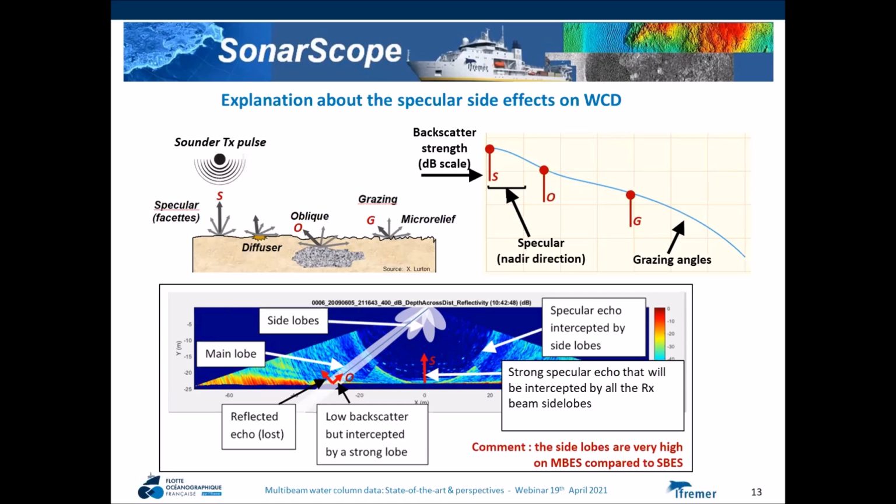The sounder emits a short acoustic wave, which is a constraint in the transversal plane of the ship. This acoustic pulse is scattered in many directions when it collides with obstacles. You see, the sound is arriving here, and you have echoes going there, and an echo going back to the sounder.